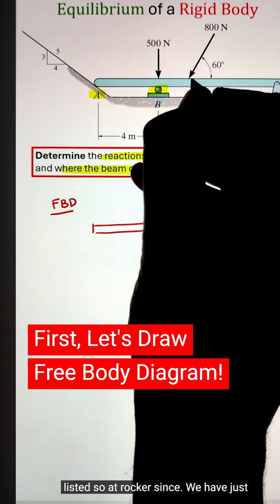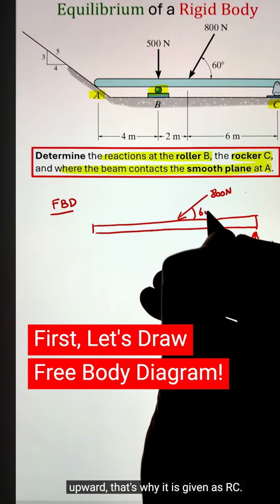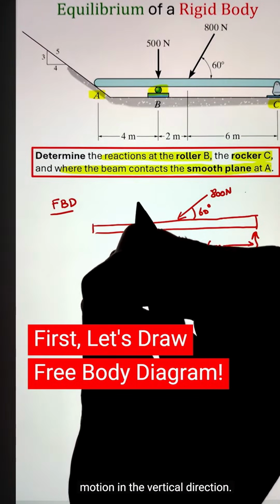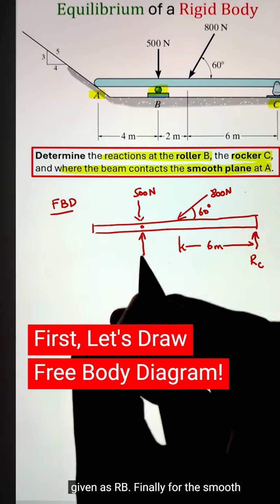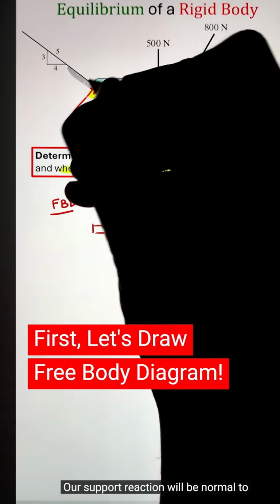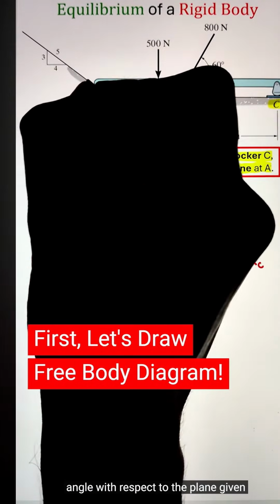At the rocker, since we have just one support reaction acting vertically upward, it is given as RC. Whereas for the roller, again, we have one support reaction as it limits the motion in the vertical direction. That's why I have a force going upward given as RB. Finally, for the smooth plane, since the plane is at an angle, our support reaction will be normal to the plane, meaning it makes a 90-degree angle with respect to the plane given here.